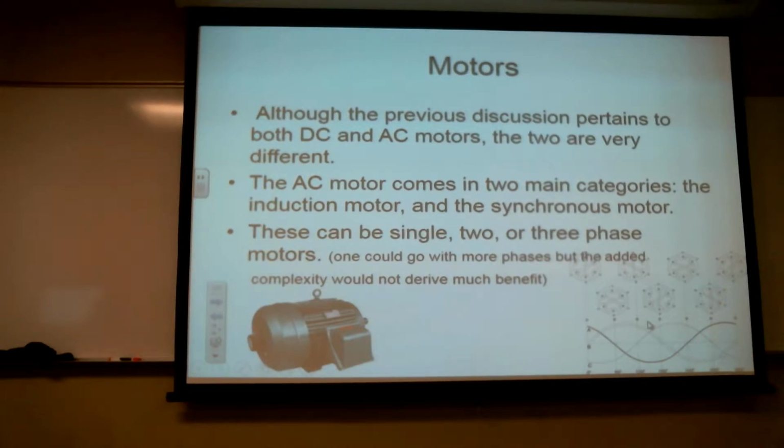Well, an AC motor will work off of both of those. The downside is if we're just using the single phase, whether it's 220 or 110, the motor doesn't know which way to go. And in fact, unless it happens to stop in just the right spot, it probably won't be able to start all that well.